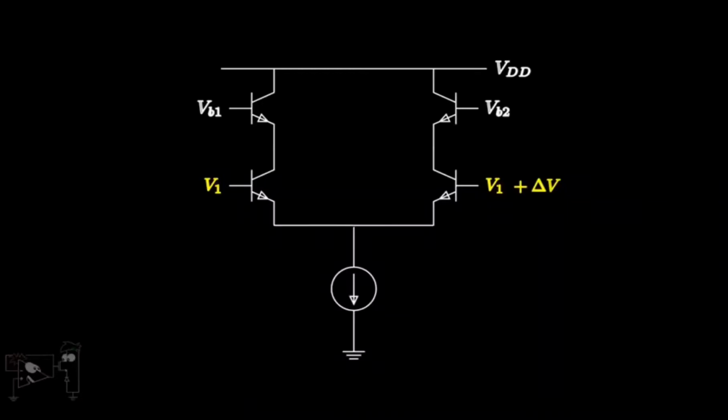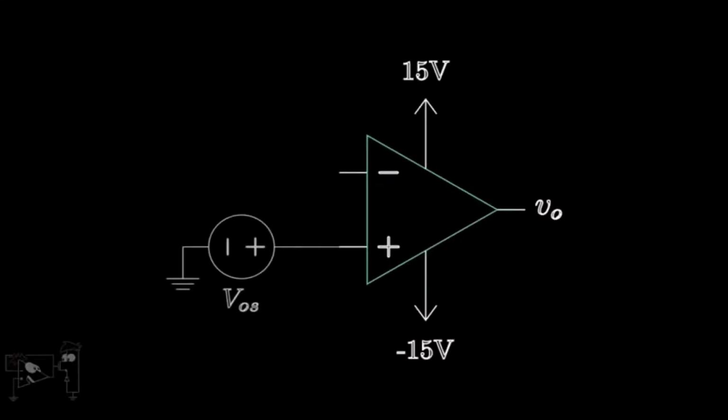We can cancel the effect of the input offset voltage by applying a differential input of the same value in the opposite polarity. Thus, the input offset voltage VOS is defined as the differential input voltage we are required to apply, so that we get 0 voltage level at the output. We model the input offset voltage by a voltage source of value VOS, applied to any one terminal of the op-amp. As input offsets are arbitrary, we cannot determine their polarity beforehand. Hence, we can model the offset voltage at any terminal.